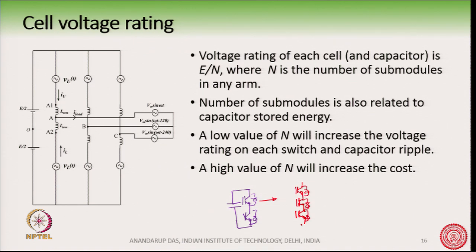Okay. So, some manufacturers have this. This one IGBT is not a single IGBT, but several series connected IGBTs. Now, this cannot be directly said. It needs to be simulated, and we have to find out what the complexity is, what the loss is. Remember, the loss is very important, because we have a large number of series connected devices.